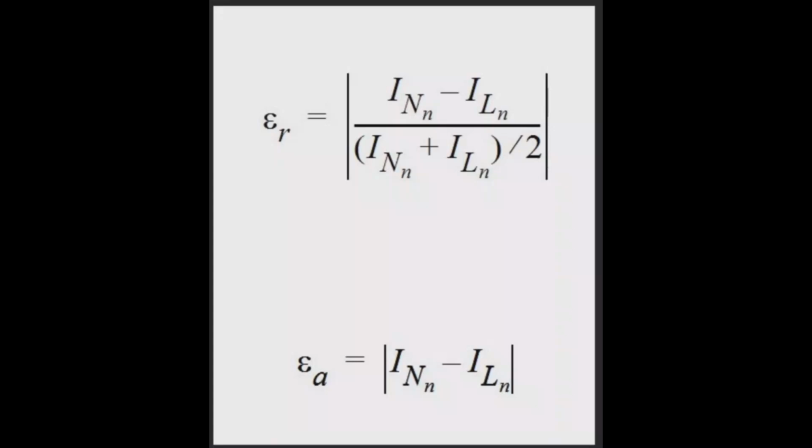In Microwave Office, I think we have a very good way to do that. It's one that I came up with a long time ago, and it works very well. So it comes down to this. Suppose we took a look at the absolute difference between the current in the linear part of the circuit and in the nonlinear part of the circuit. So I sub capital N is a nonlinear circuit, and N is a vector component. That's a certain frequency component at a certain port. And the same for the linear component over here. If we just took the magnitude of that difference